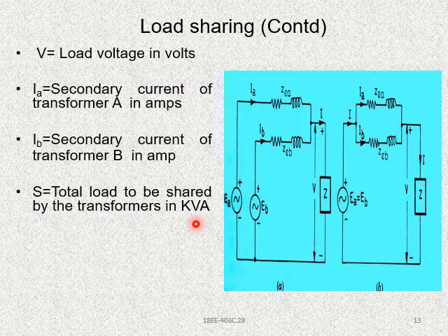We have the power equations we may have studied in electrical circuits, like S, P and Q. S is for kVA, P is for kW and Q is for kVAR, where S is apparent power, P is active power and Q is reactive power. There are three kinds of power. The transformer is always measured in kVA, that means apparent power denoted by S.